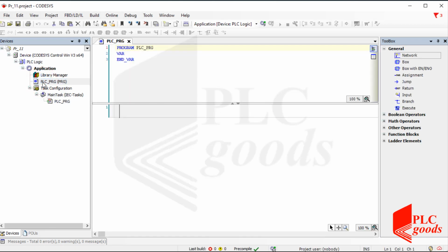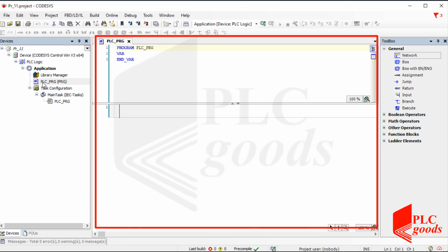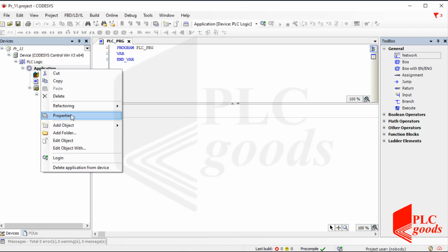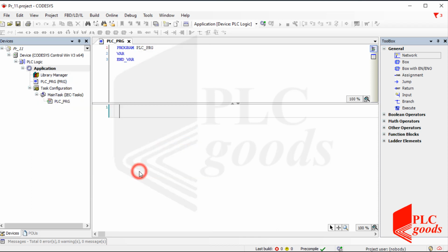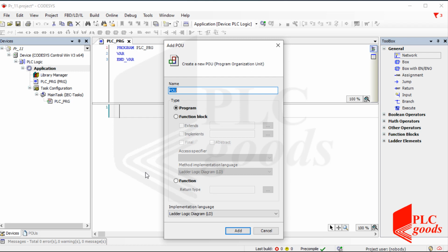Alright, there are two tanks with the same performances. The whole of my program can be written here, inside the main POU. Instead of this simple way, let's see how function blocks can be used to make a more efficient program. During the previous video, the last item, function, was explained and used to implement a mathematical expression. In this project, I need a function block. It works like functions, and during the programming step, I'll show you the main difference between function blocks and functions.